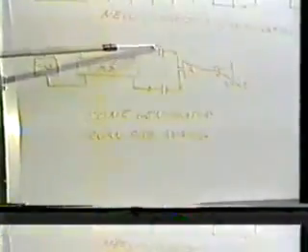So a negative conductance, which may be a cathode follower with a capacitor in its cathode, or the capacitance of the line producing negative transconductance and oscillations. It could be a Hartley oscillator. It could be a multipactor tube. There's many different ways to produce negative conductance or resistance. This is connected to one end of the line to maintain the harmonic oscillations in the line. And then the dielectric end is very lightly coupled to an amplifier, which of course produces the sound in the speaker, and your musical keyboard, of course, would switch these things in as necessary to produce the music.